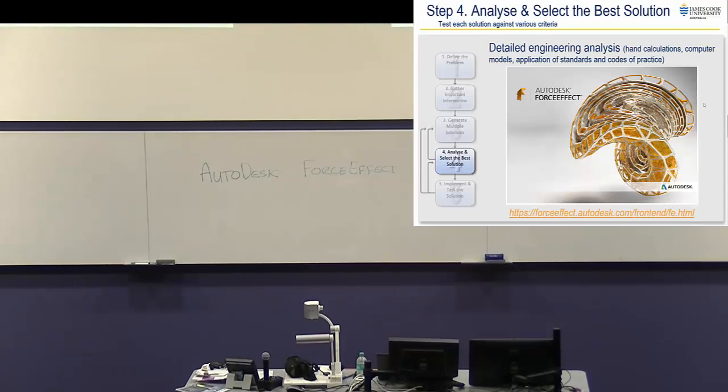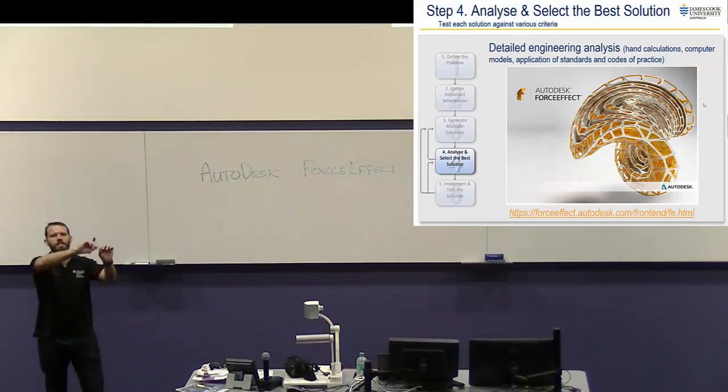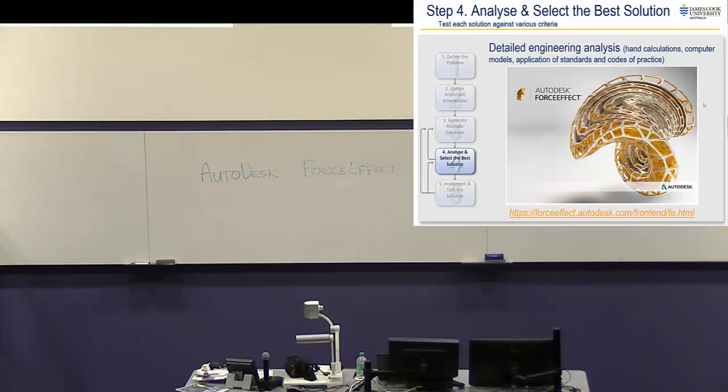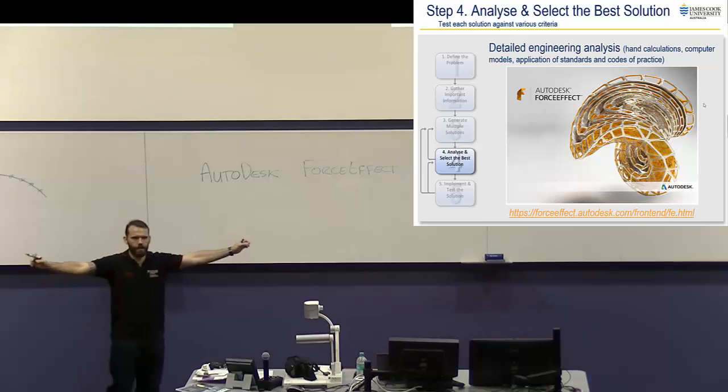Cool? So guys, when you actually do this, obviously it talks in straight beams, right? So if you've got an arch, you'll have to compose it in short bits of straight beam. So if I did an arch with short sections like that, now obviously if I have pins here, that's going to be basically a big loose wobbly chain, right? But if I did those weldments, that's fixed, and so that will actually behave as if it's a big curved solid structure, and it won't go anywhere, okay?